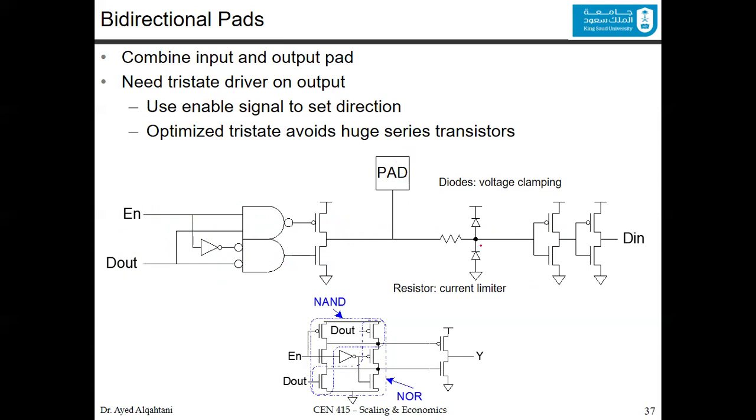Now for this circuit to work, we actually can do it this way. You can see that this one is actually this one. And we have the NAND like this. We do some sharing. So this is the NAND. This is static CMOS design for the NAND, as we discussed. And here is the inverted input AND, which is a NOR. And this is the NOR here. You can see the parallel in the pull-down.